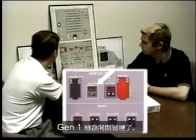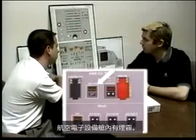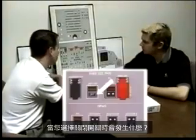Gen 1 line. You get smoke in the Gen 1 line switch. What does that indicate? There's smoke in the avionics bay. It's going to be associated with a blower fault and an extract fault as well. What occurs when you select the switch to on?